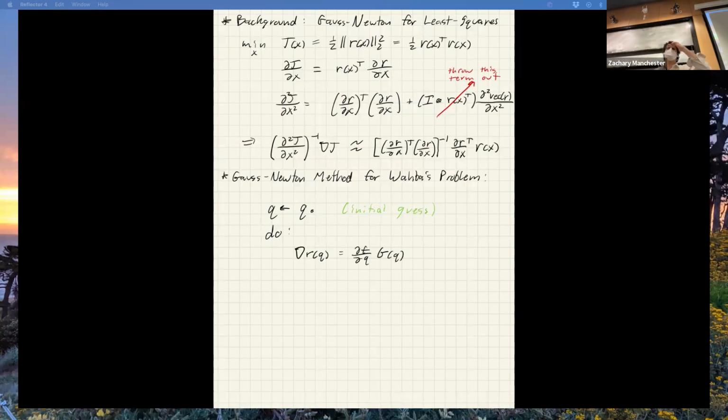Then we're going to compute our Gauss-Newton update. And we're going to use all the standard stuff to do that. So we're going to compute this phi, remember, this multiplicative 3D thing. And that's going to be this guy. And then I'm going to update my Quaternion by doing the multiplicative update thing.